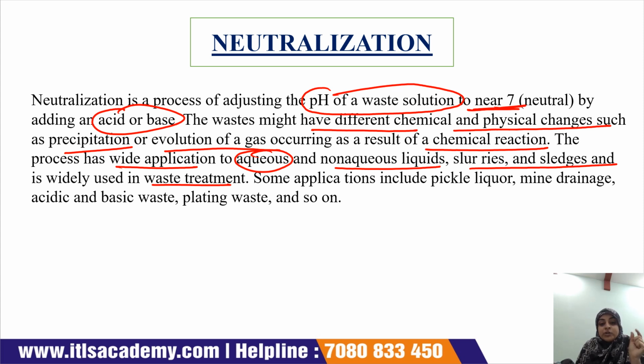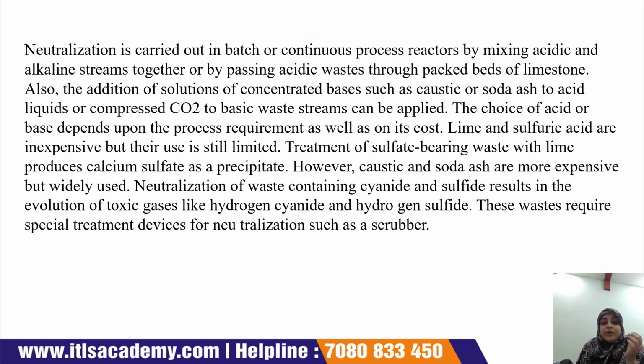Now the different applications of neutralization include pickle liquor, mine drainage, acids, acidic and basic waste, plating waste, and so on. Neutralization is carried out either in a batch process or in a continuous process in a reactor, by mixing an acidic solution and an alkaline stream together, or by passing an acidic waste through a packed bed of limestone.